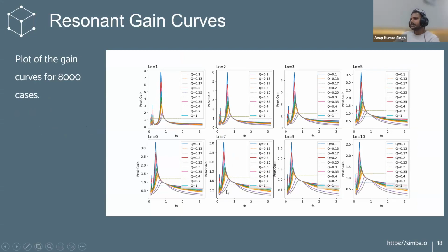Now you have to choose the minimum and maximum frequency of operation, to counter the line and load regulations. Here you can see the maximum gain, and the peak gain is above this line, so it is well and good. You can see where it is intersecting the frequency axis. Suppose it is around 0.6 or 0.7, suppose it is 0.7. If you are using matplotlib, you will directly get the values here, where it is intersecting this curve.